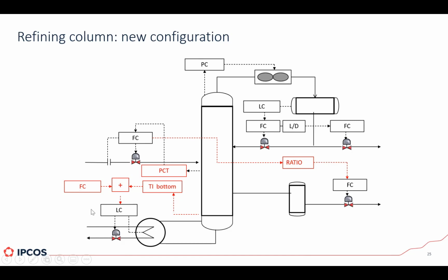If you can change the amount of steam that goes through the reboiler, then you're changing basically everything in the column. If you increase the amount of steam, for example, then obviously this sensitive temperature will try to increase. And then to compensate for that, the column will bring more feed in. So this is indirectly the way they were controlling the feed of the column, and that worked very well.